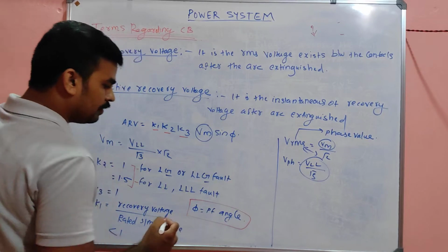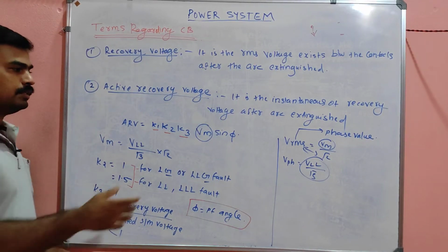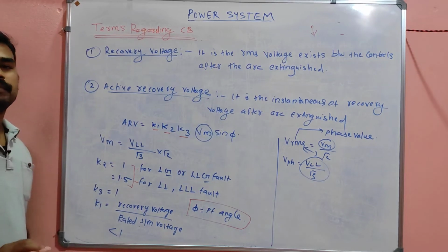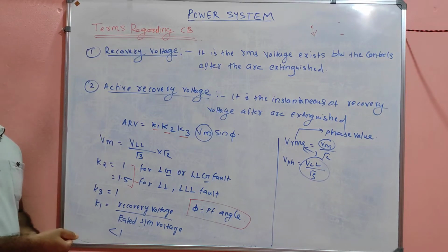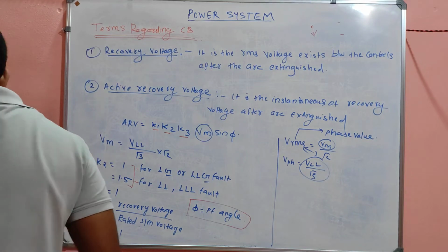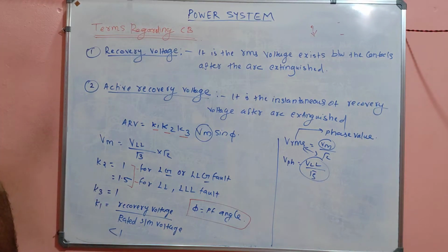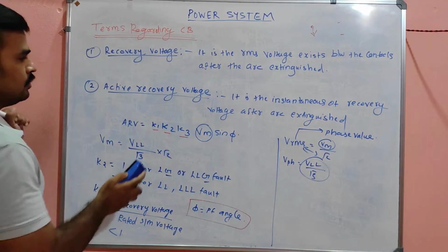You have to note one important term here, my dear. The active recovery voltage depends upon the power factor of operation. That also you have to note down. So that's all about the active recovery voltage. Okay. Next one.